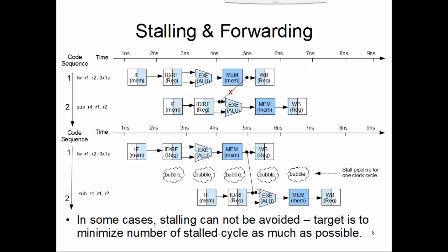We minimally push the instruction execution such that the time when you need the updated data, at the beginning of the exe cycle of the second instruction, falls about the same as when the data is produced by instruction 1.